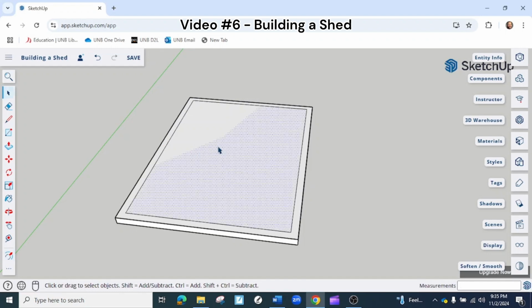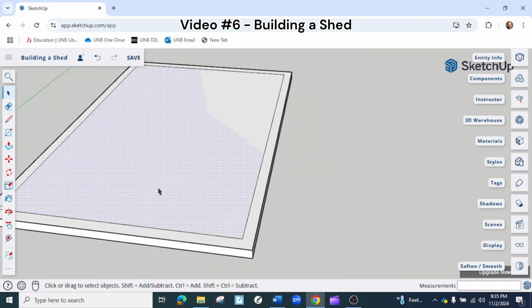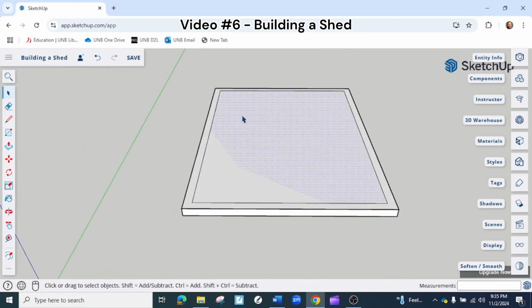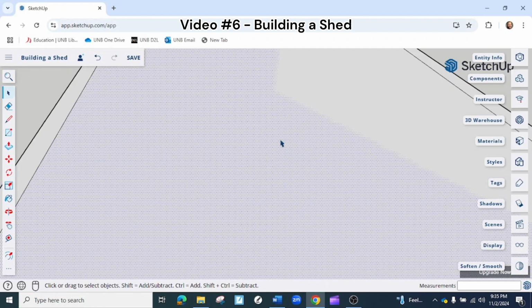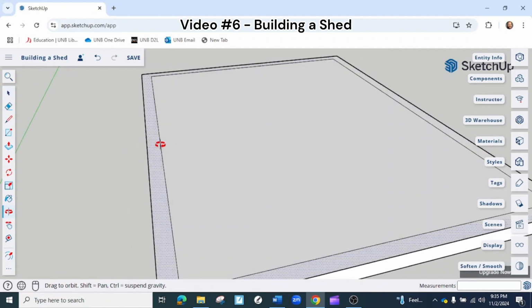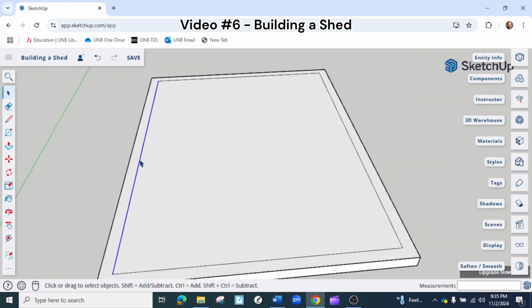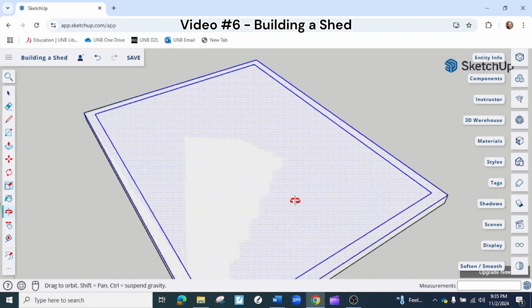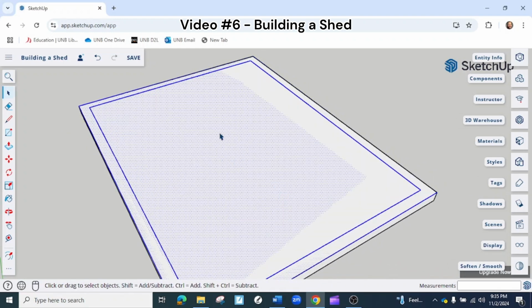Now, there is still a face in here. There's still a blanket that you can see kind of on my screen as these blue dots. There's also that in here around the outside perimeter, and they're separated by this line that goes around the outside. If I triple click, right, it's selecting all of that geometry. I do not want there to be something here in the middle. So I'm going to only click that. So just click that middle part and hit delete.